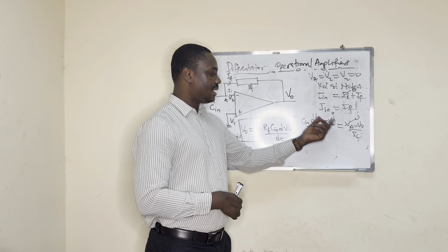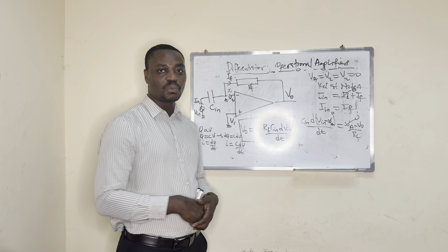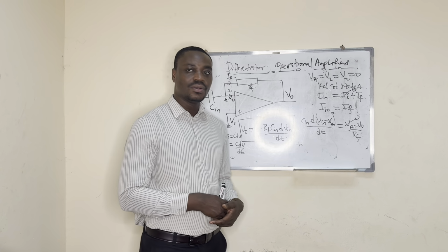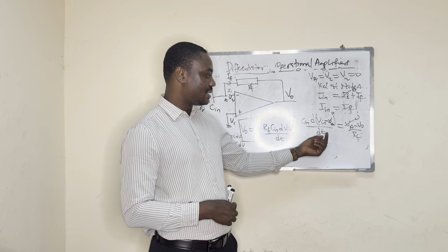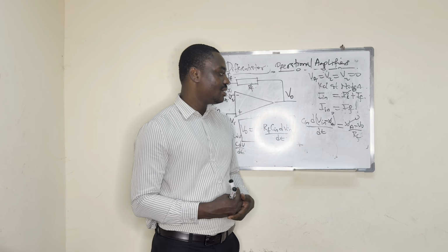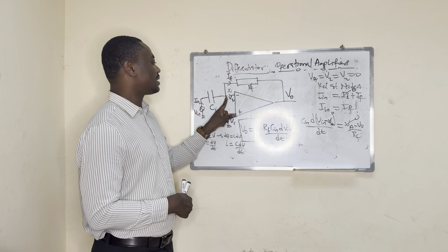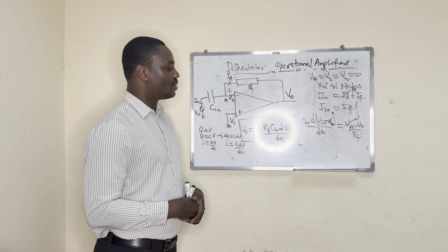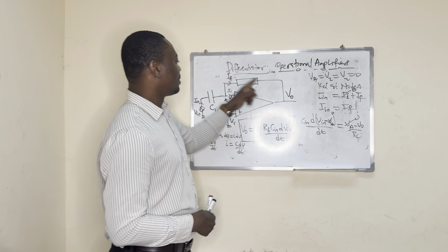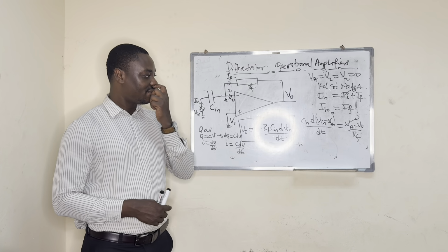Now we come back and apply that idea. The voltage here is the potential difference between V_in and the node voltage at node A. So we get this relationship, and that equals I_F, which, again using potential difference, originates from node A, so we have V_A minus V_O over the resistance between the two voltages, which is R_F.